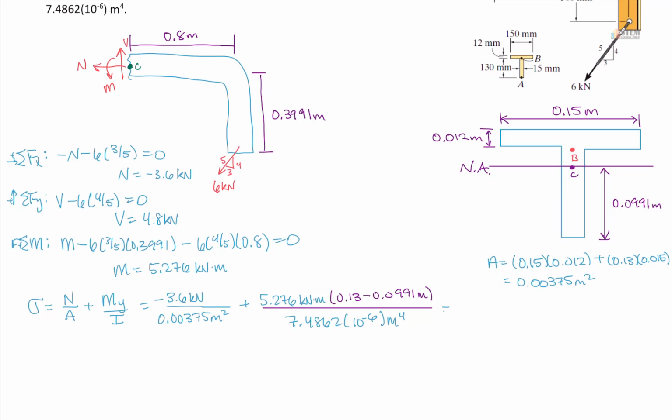And then let's go ahead and calculate that value. And what we get is 20,817.2. And then that would be Pascal. Actually, it's not Pascal, it's kilopascal. All right, so now we've got that in kilopascal. And if you wanted, you could put it in megapascal. Let's go ahead and do that so we don't have this huge number. So just divide by 1,000. So that'll be 20.817 megapascal. All right, and it's positive, so overall we have a tensile stress at B.